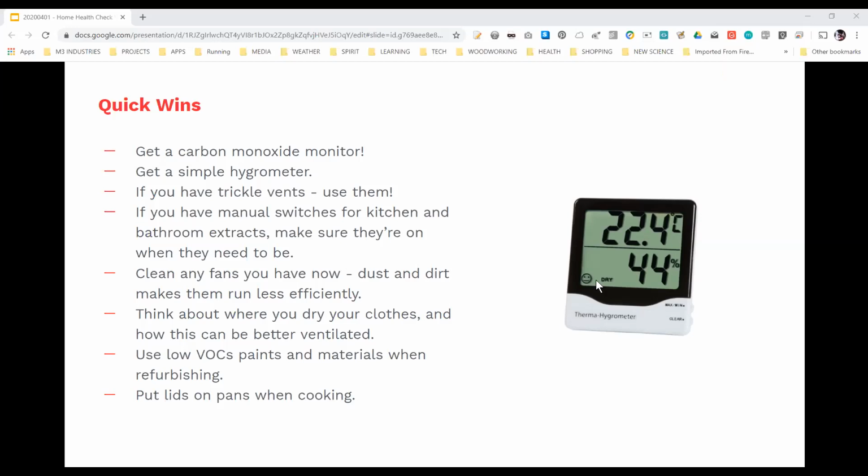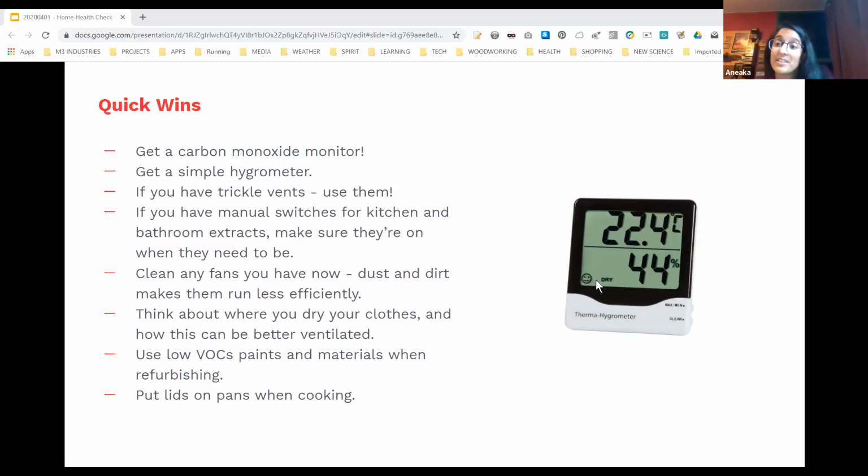The UK building regulations of 270 millimeters isn't really enough to give you a proper woolly hat on your house, and I really aim more for 400 or 450, because that's really getting you down below a U value of 0.1 for the whole house. I'd really support that. We always recommend about 400 mil of insulation in the loft. So, yeah. Absolutely. Thanks, Andy. No, that's really very good.